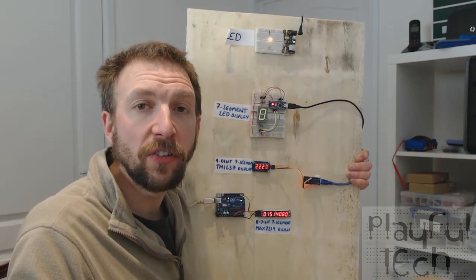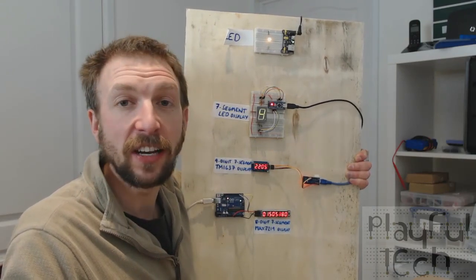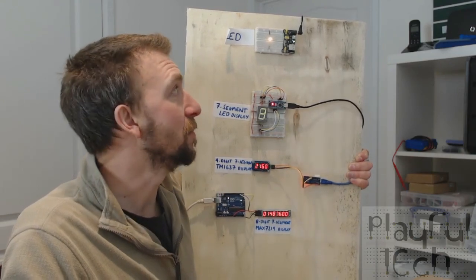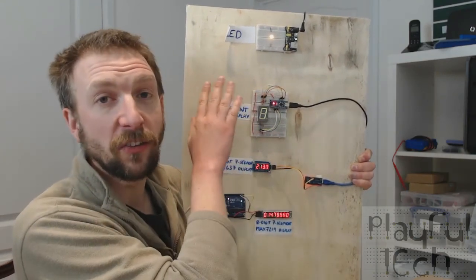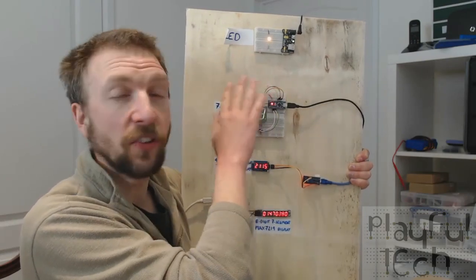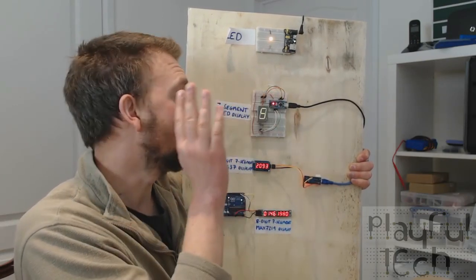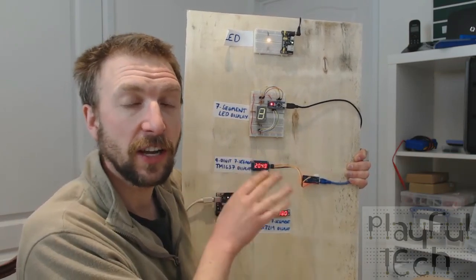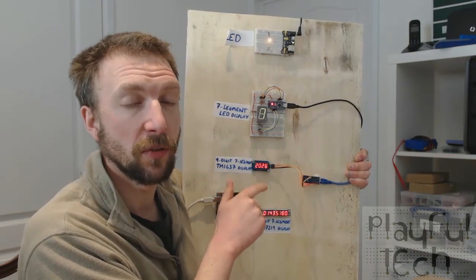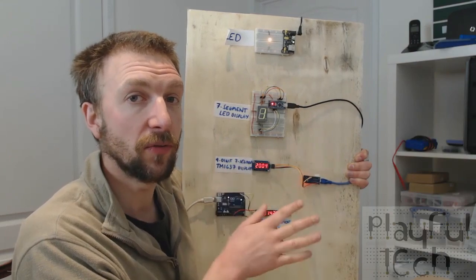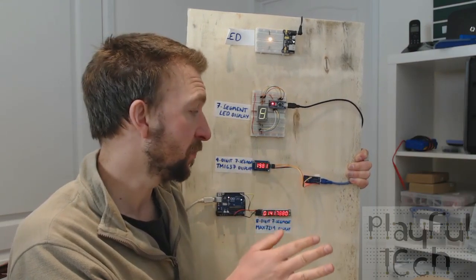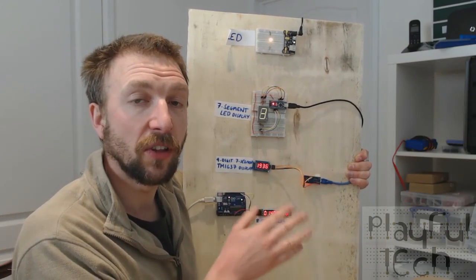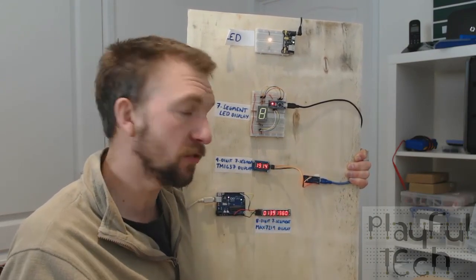So that's about all there is to say about LEDs and LED displays, really. Just to summarise, obviously make sure your LEDs are plugged in the right way around. Always use a resistor of the right value. If you're using a segment display like this, check the voltage requirements of the module, whether it's 3.3 volts or 5 volts, or whether you can use either, and plug the pins in correctly, and then you simply have to use the library for the controller chip on the back.